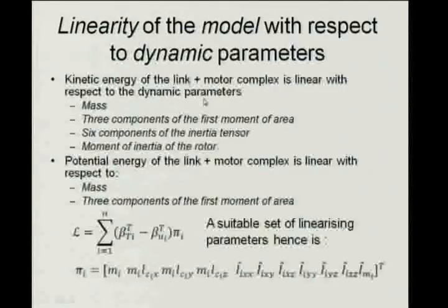Okay, so it's used in many ways like this. And then you can essentially go back and show that it is linear with respect to the inertia dynamic parameters. So, there is a route to estimate these dynamic parameters, because some of them are very difficult to estimate through individual measurements. So, you form a reasonable estimate of it and then you run your robot, you measure the torques and the accelerations at the joints, and there are standard algorithms which you can run and you will get better estimates, so that improves your model. So, subsequently you will have better performance.